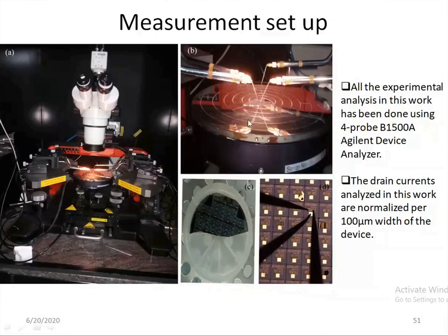This is a chuck of the device analyzer. In the case of a DC analyzer, you can find that this is a chuck that can be heated, so temperature analysis can also be done using the chuck. Here we have loaded the wafer on the surface, introduced the probes onto the source and the drain of the device, and then checked the device sensitivity by applying the gate voltage.